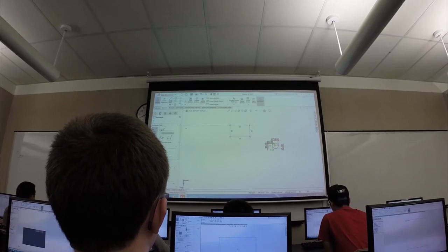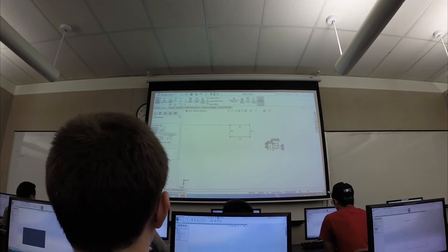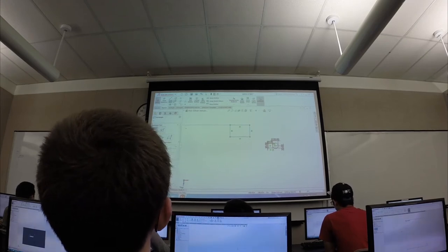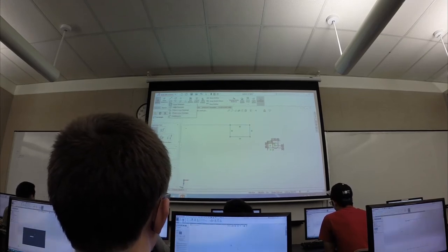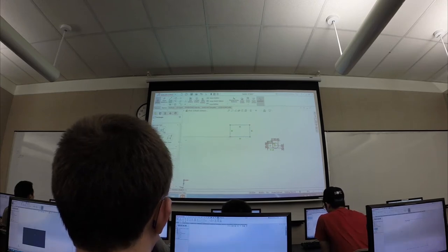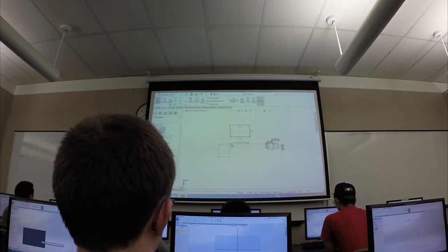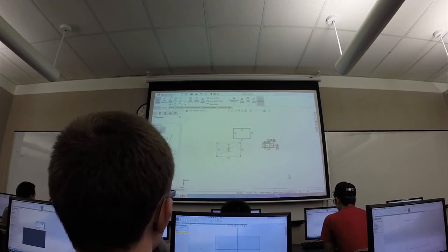And then right here, in your property manager, you see all these different rectangle types, right? It's the same menu that drops down from the drop-down menu. We're going to try making a center rectangle. So this rectangle was defined corner to corner, right? This one acts much like how the circle was drawn. It pinpoints the center of the rectangle, and then it brings it outwards like that, equal on all sides, in terms of how you do it. So we're going to draw that there.